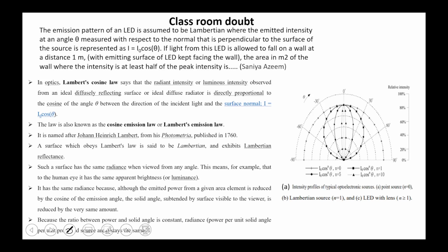In the assignment, if you have any doubt, you can ask that. Yes, sir. I have one doubt. I'm having doubt in highest spectral efficiency. I'm calculating the spectral efficiency for 16 QAM, having a bit rate of 10 baud rate, and I'm getting the spectral efficiency of each of them the same, 2 bits per second per hertz.